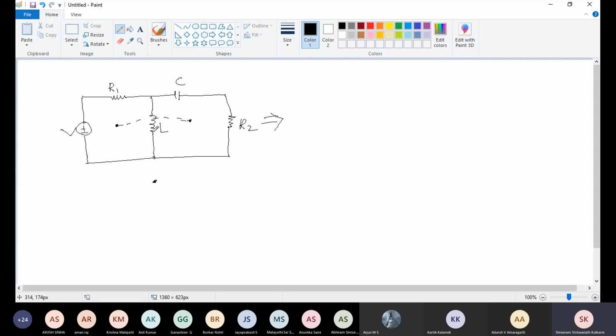So now connect all internal nodes to the external node by a dashed line, crossing all the branches. It means first place the nodes inside the loops and one node outside the loop. After that, connect this node to the reference node by crossing the branches like this.